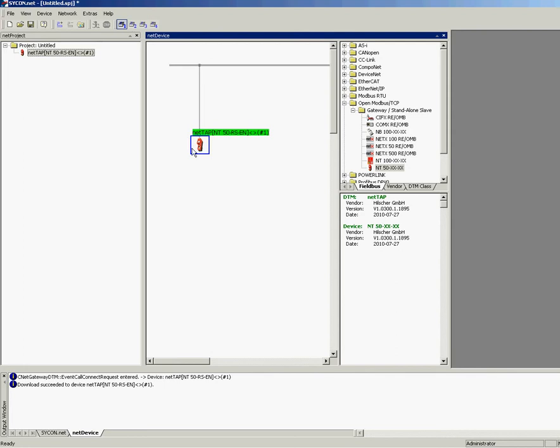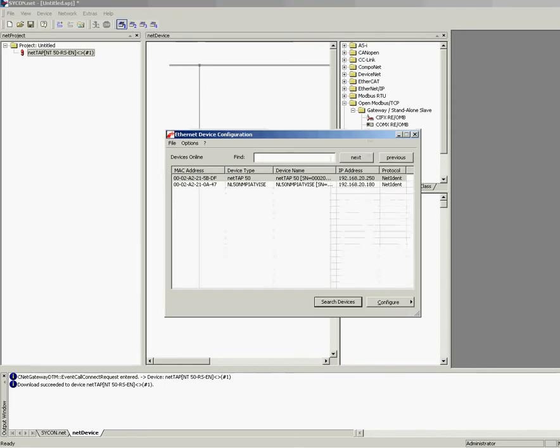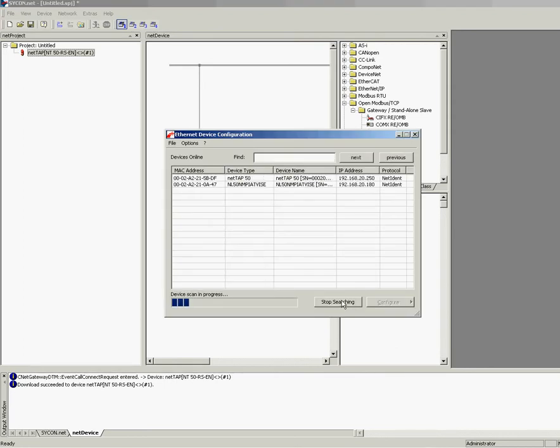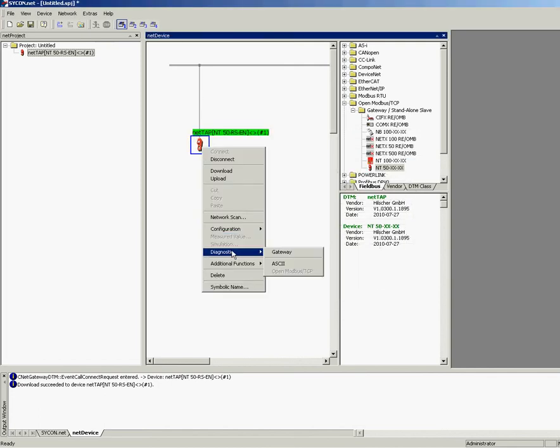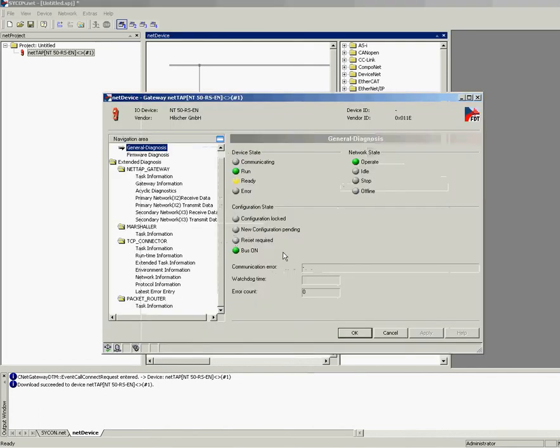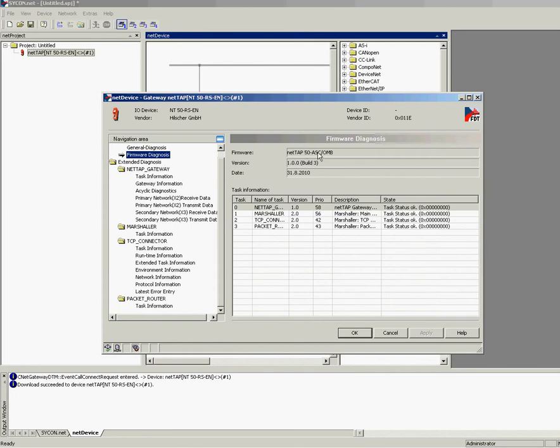So now we can start our peripheral utilities like Hyperterminal or ModScan32. You see here I make another scan, and this time it hasn't forgotten its IP address. Look just into the diagnostics window. The LEDs are green and yellow. Firmware is working. Everything is fine after the download.